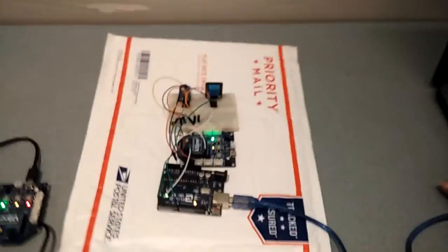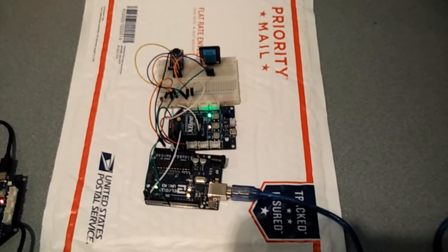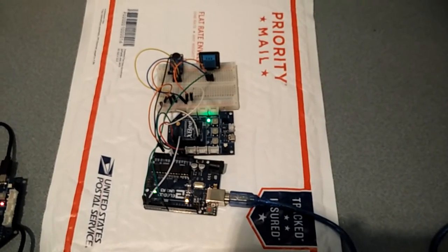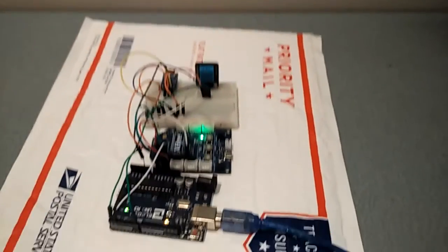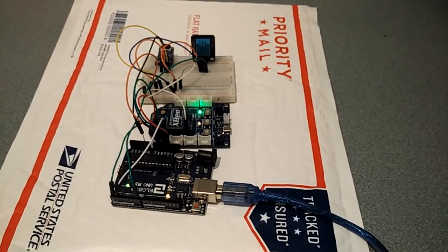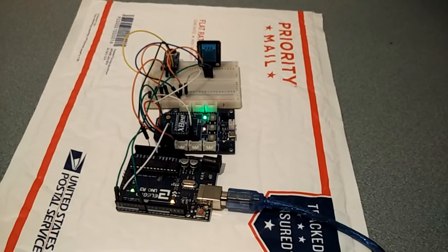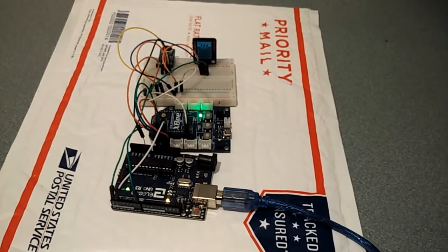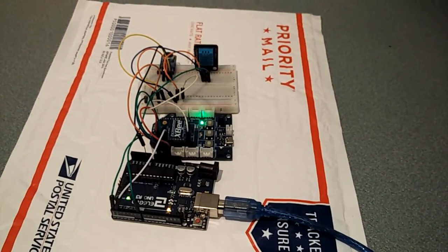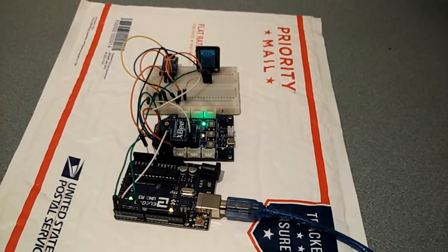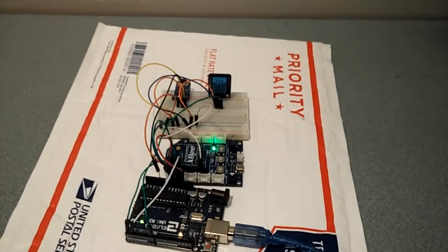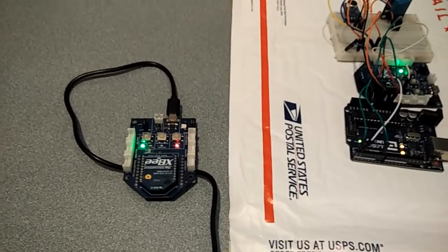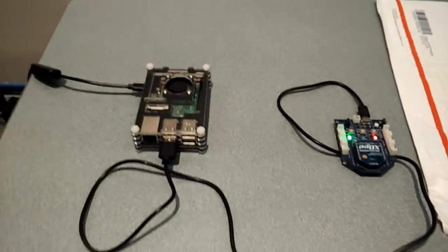Moving on to the setup. This is our sensor node. We're using an Arduino Uno board and a Zigbee transmitter for this. The sensors that you can see wired up on the breadboard are the temperature and vibration sensors for the motor. What happens here is that the Arduino board processes the data from these sensors and sends it over through the Zigbee to this Zigbee receiver, which is in turn connected to the Raspberry Pi.